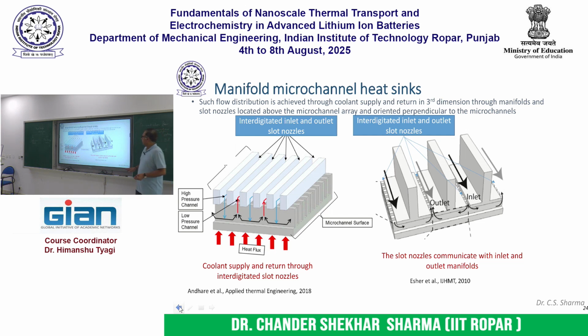Okay. And another thing that helps in improving the heat transfer efficiency is that if you look here, the liquid is coming down and impinging into the channel. So this forms a configuration of an impinging jet. So you get the benefit of impinging jet heat transfer, you get the benefit of flow through the microchannel, and because the flow length is minimized, it reduces the overall pressure drop. So the pressure drop is lowered, heat transfer is improved, and that is what any thermal engineer would be looking for. Okay.